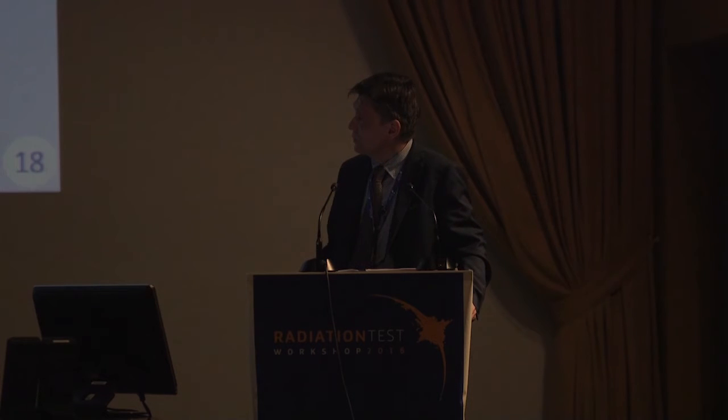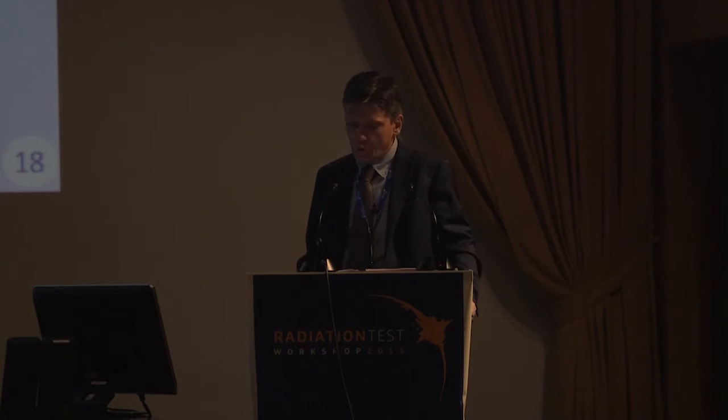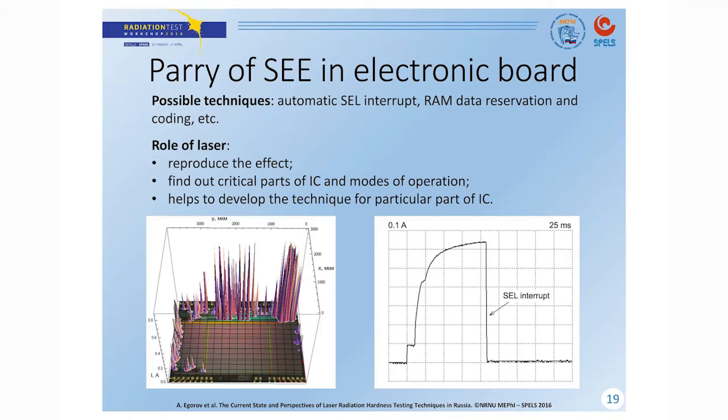And also we can use tight synchronization of the laser pulse with the timing diagram of the IC to test the radiation hardness parameters at various moments of the timing diagram. So there are some supplementary applications of laser techniques.